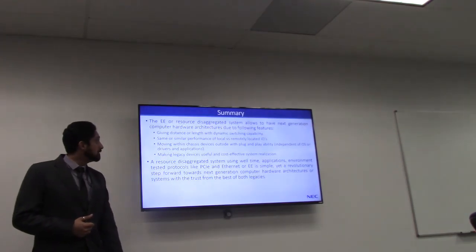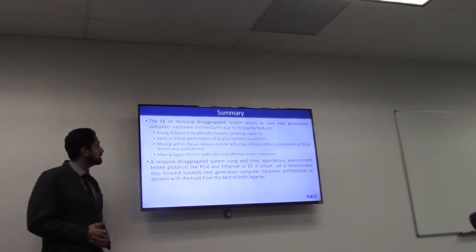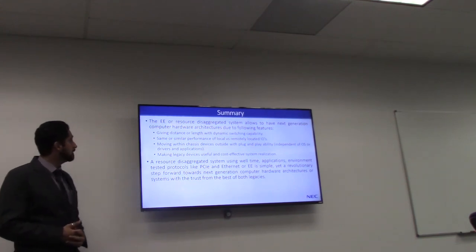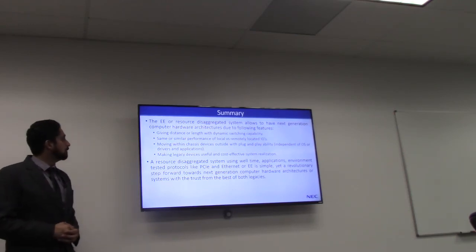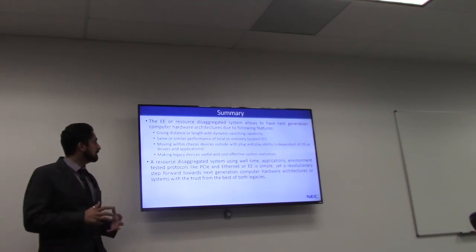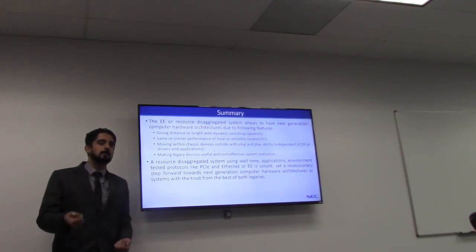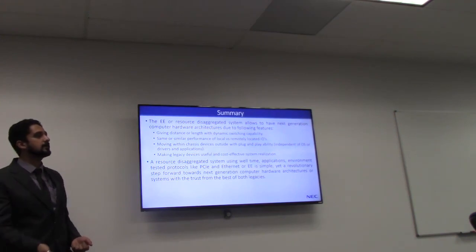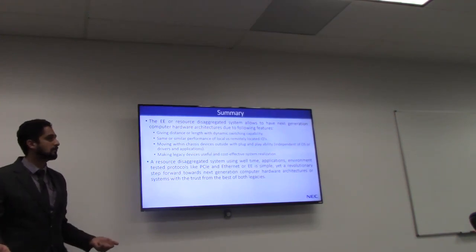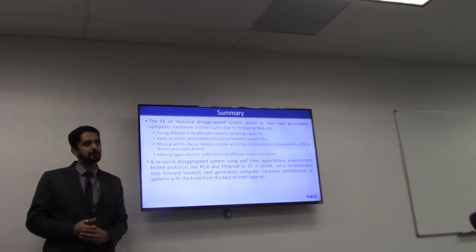So that means we can actually have a real-time data analytics system using PCIe or PCIe switch extension over Ethernet. So summing it up, Express Ether gives us distance capability and dynamic switching. It has the same performance as local versus remote. Moving within chassis devices is plug and play. We support hot plug, so you can plug out your SSD and plug in on the fly without shutting down the system. And most of that is the best use case.